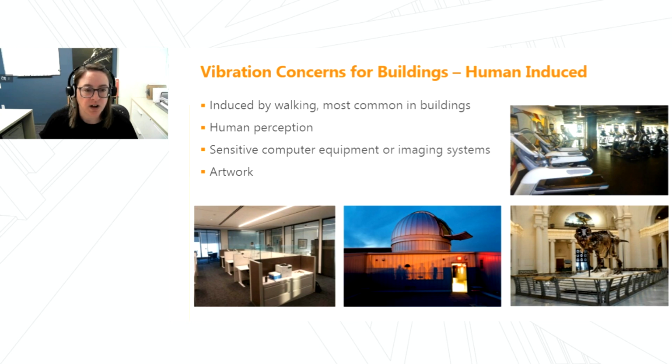As modern buildings are designed with more open spaces and fewer columns, the floor systems become more flexible. And this may be allowing vibrations to travel farther in a building and could be more perceptible. Also within these large areas, there are a lot of typical setups with cubicles, and the adjacent walls are often glass and stop at the ceiling line. The vibrations of the floor can cause sway of the partitions.